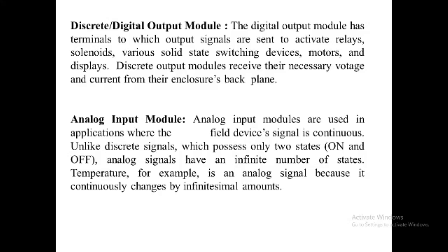It passes the signal through an isolation circuit, which completes the electrically isolated transmission from an AC signal to a DC logic level signal. And this logic circuit then makes the DC signal available to the processor through the rack backplane data.